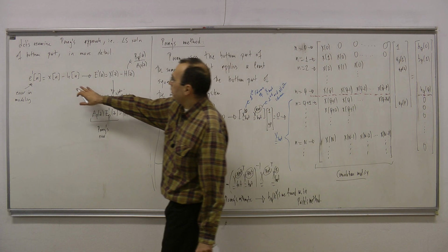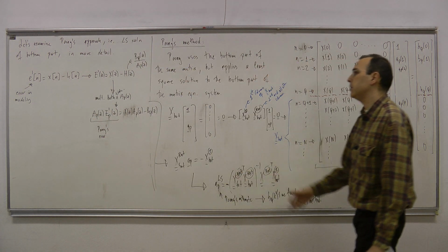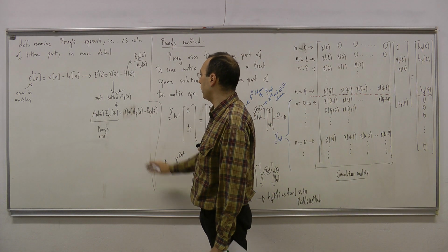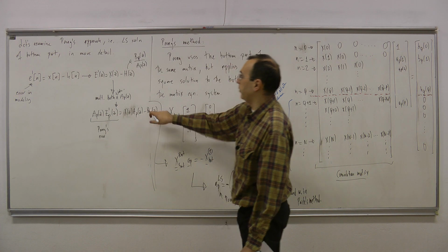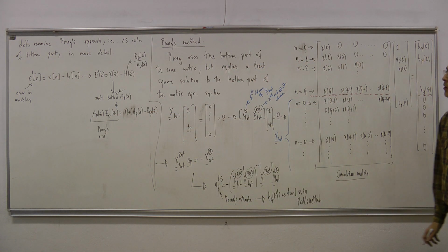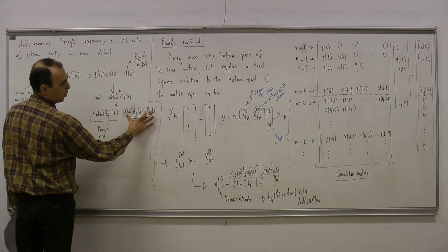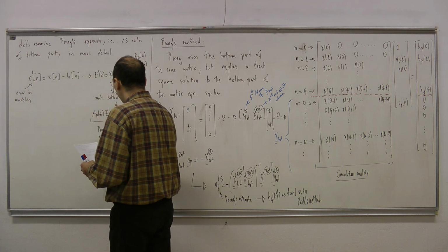That observation is related with this Prony's error definition or Pade's error definition. Now a's and b's are separated, and I want this to be equal to 0 polynomial, because it's a polynomial in z. So I would like to equate the coefficients such that this is as close as possible to 0.